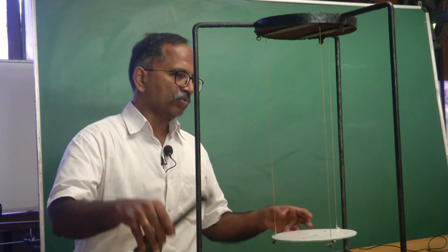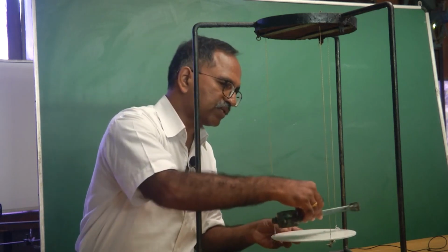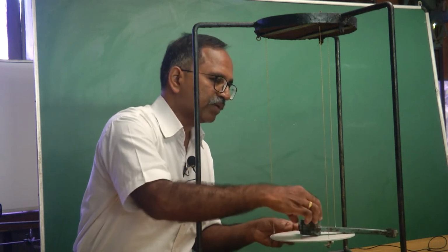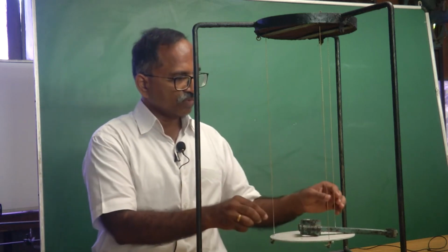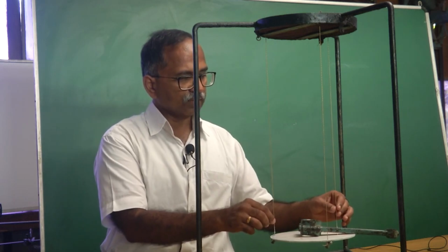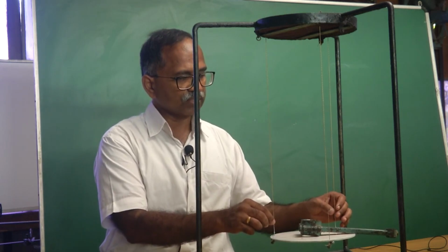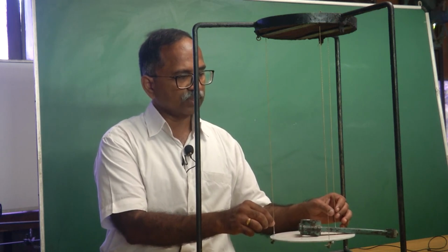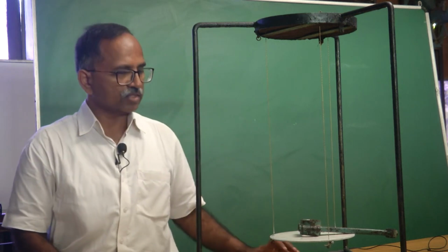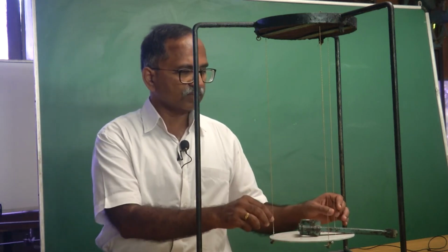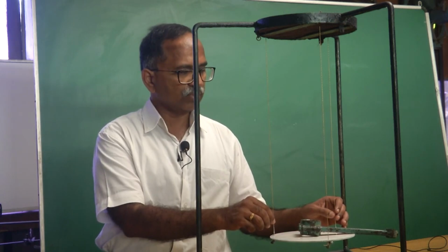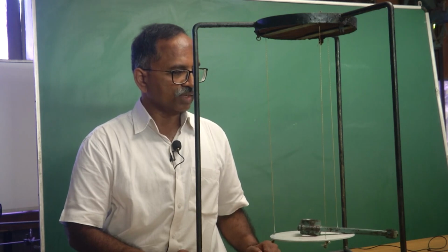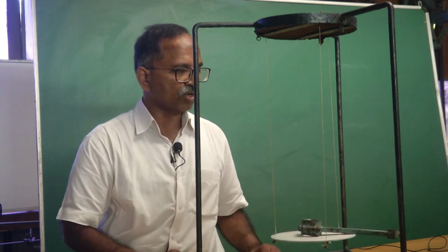Okay. So, I shall just place this connecting rod with its axis aligned to that of the plate, and we shall try and record the oscillatory motion and therefore, the period of oscillation. As we all know, for the derivation of the governing equation and the expression for natural frequency, the underlying assumption is small amplitude of oscillation, and therefore, it is imperative that practically as well we give a very small angular displacement, so that the oscillations are with small amplitude.